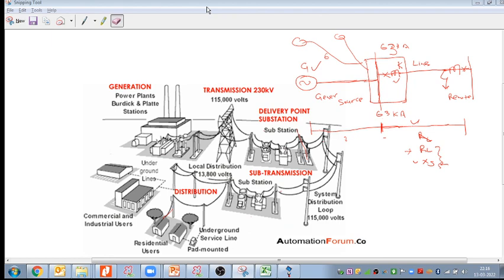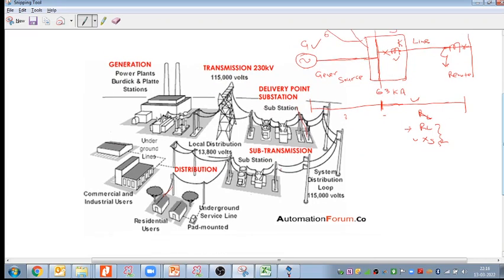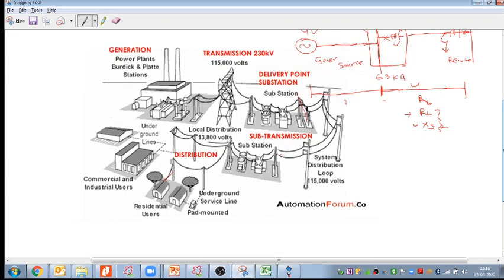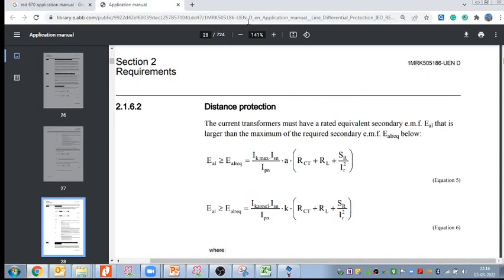No, well, it depends on where exactly the fault occurs. If it is a zero crossing of the voltage or some other point, like say the peak of the sinusoidal voltage, you get the maximum DC component.